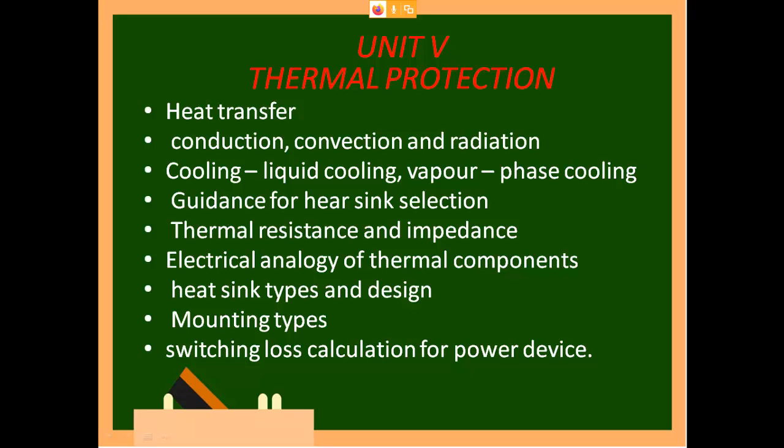Then comes your heat sink. A heat sink is the black structure you might have seen kept behind your semiconductor devices. Then we will see thermal resistance. Current will flow only through minimum resistance; similarly, heat will also flow through minimum resistance. So if you bring a heat sink made of some material which has more resistance, then heat from your semiconductor will not get transferred to the heat sink, and whatever you have done is a waste. That is why heat sinks are made of metal, because metal has less thermal resistance.